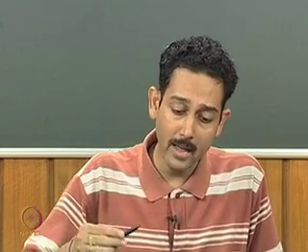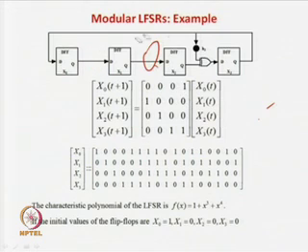Now, there is another thing which also matters. As in the case of standard LFSR, one more important thing is called the seed vector. Seed means the initial reset values. Depending on that, you can also have a series like this, no one can prevent you from that. You can have this as the seed vector, then you start from this one, and with any other seed vector, you start from that vector.